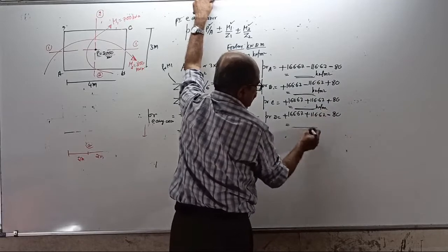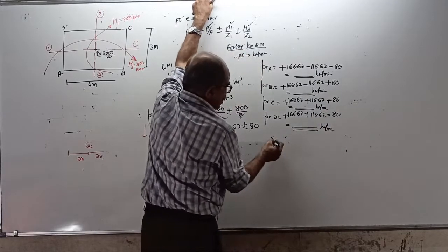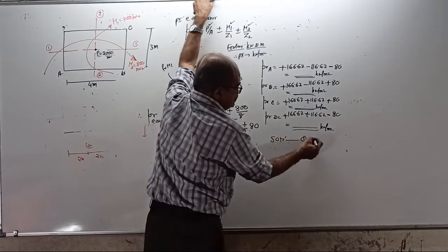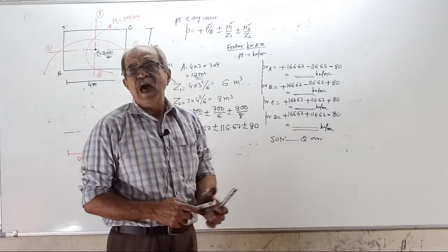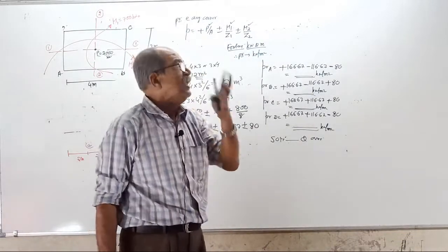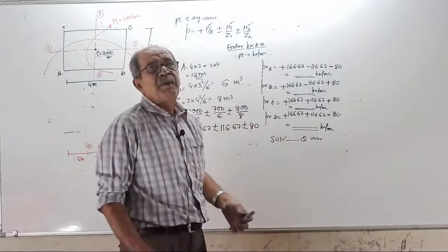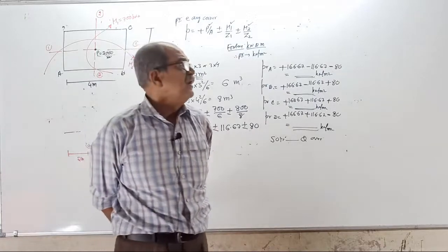Then you can make a note. Our strength of materials part of the question is over. In RCC, you have to consider the maximum pressure, which should not exceed the SBC of soil. For P by A, take 10% more weight for the footing.